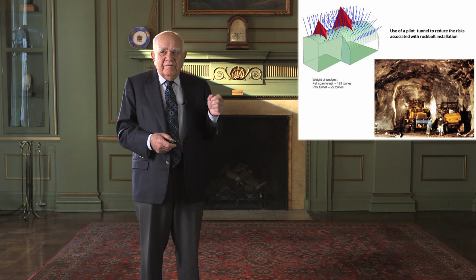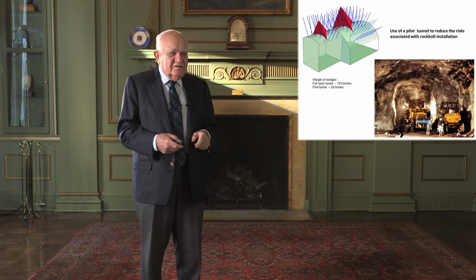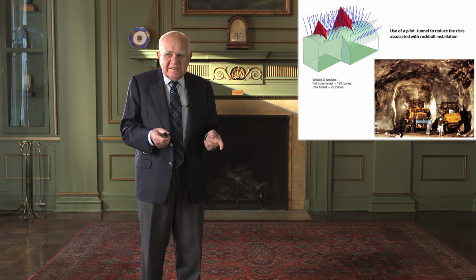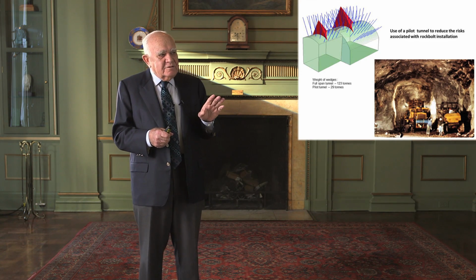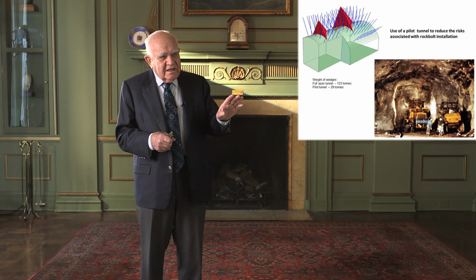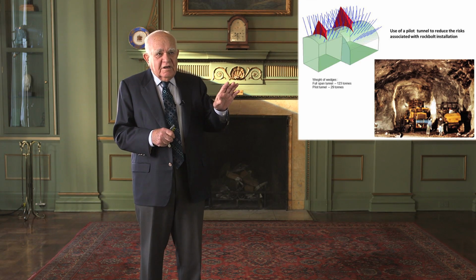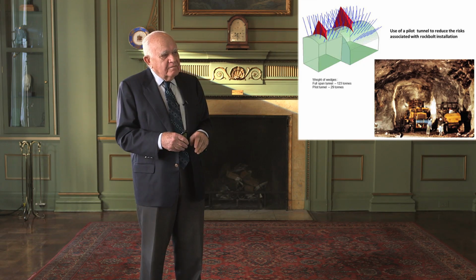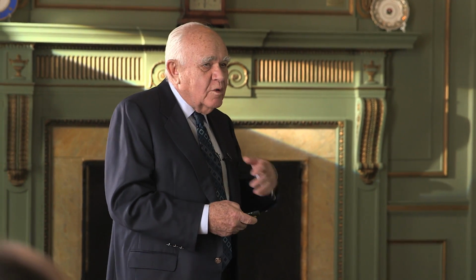But you put the bolts in for the final wedge you're expecting to occur when you open it out to 8 meters. So you do it effectively in 2 stages. You drive the pilot tunnel ahead, you support the rock overhead, and 10 meters behind, you drive the wings forward. So you're not impeding progress, the tunnel is still moving ahead at the same rate, but in 2 steps, with the pilot tunnel and then the wings. And this is a technique we'll see more and more of as I go through the lecture.